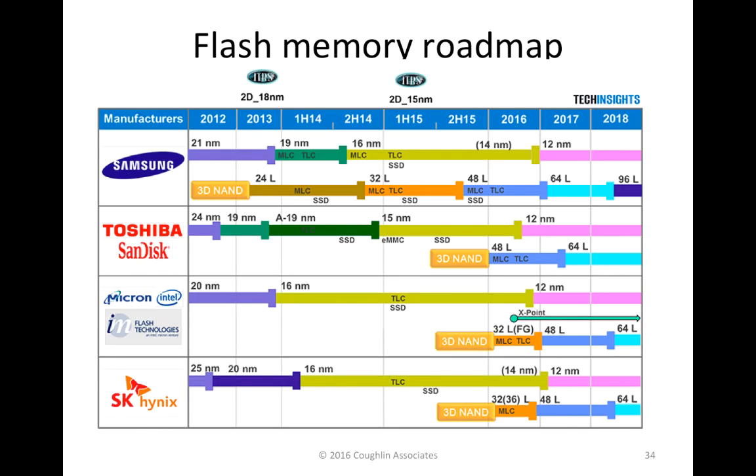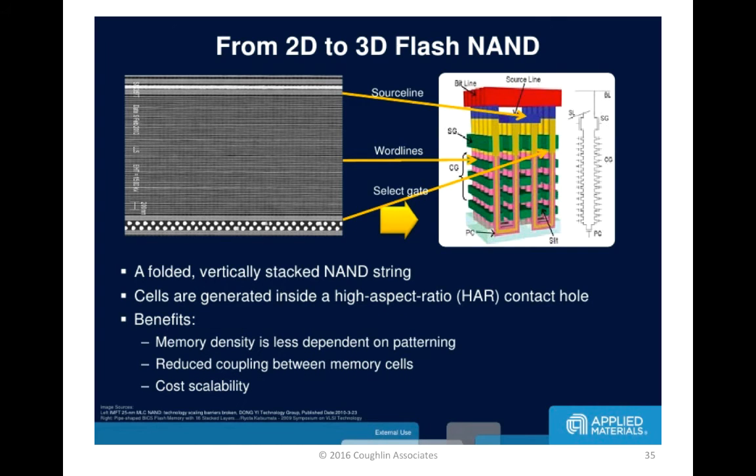Of course, the move to 3D NAND is being pushed primarily by issues with being able to push lithography to smaller and smaller features. It's easier to go in a third dimension and relax the lithographic features than to continue to push the planar NAND flash. However, these devices are somewhat harder to make.